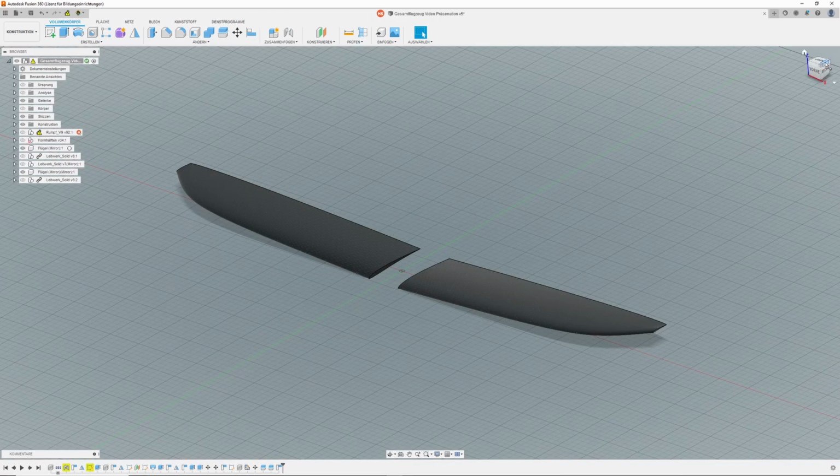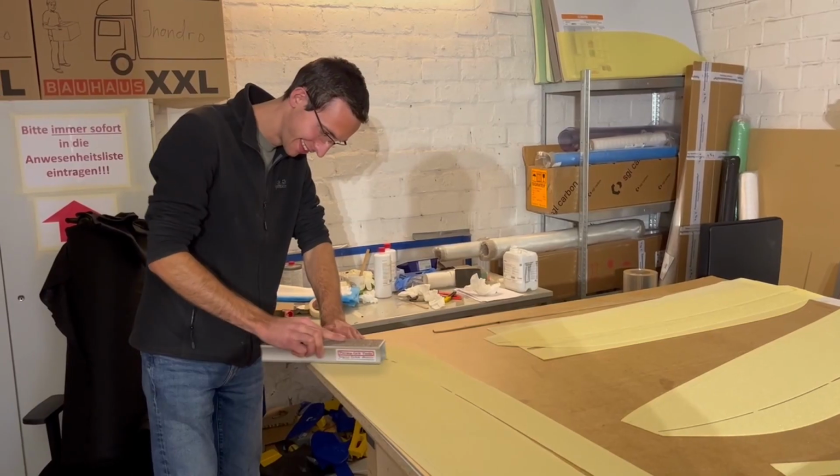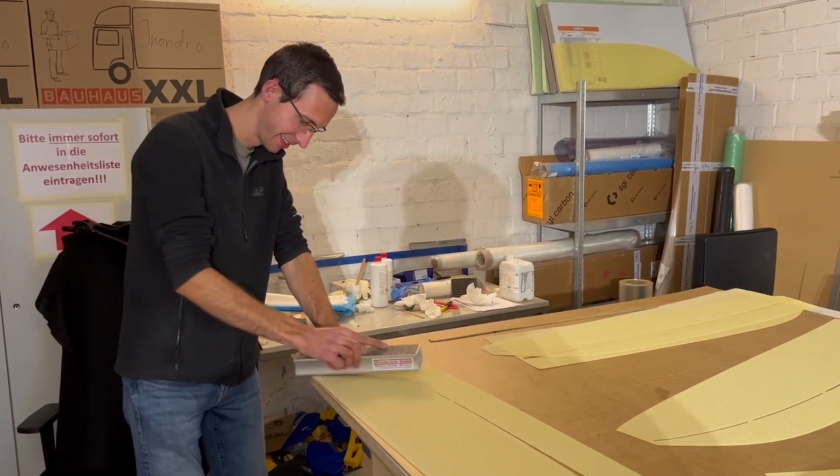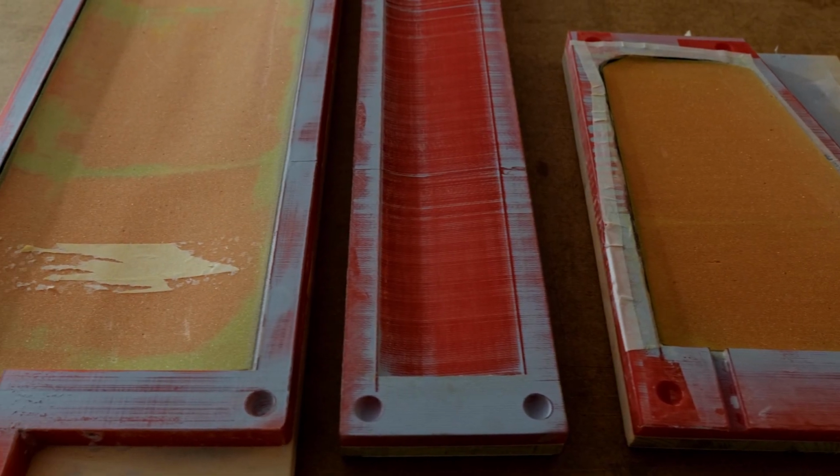The main wing was our biggest challenge. We chose to go with a similar approach as we did with the fuselage, with the major difference being that the skin of the wing would be made out of a carbon fiber and foam sandwich.